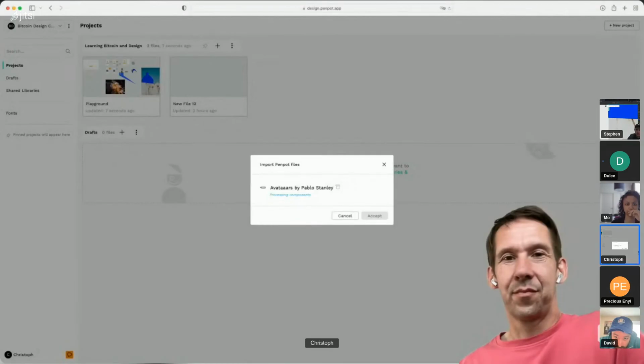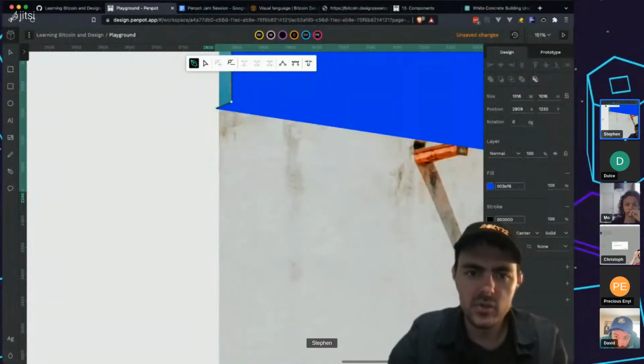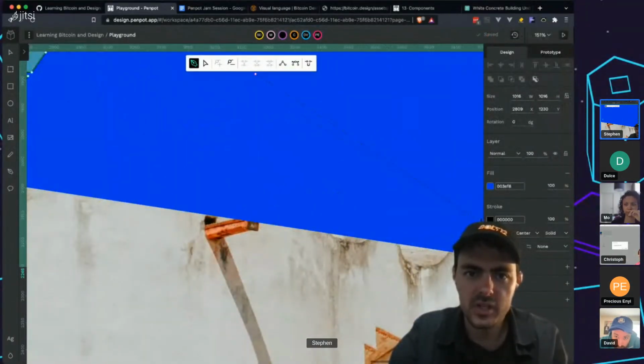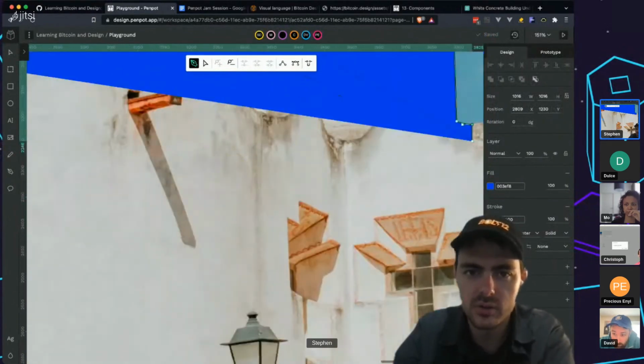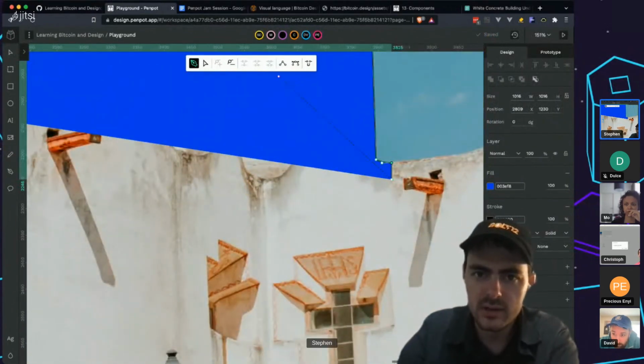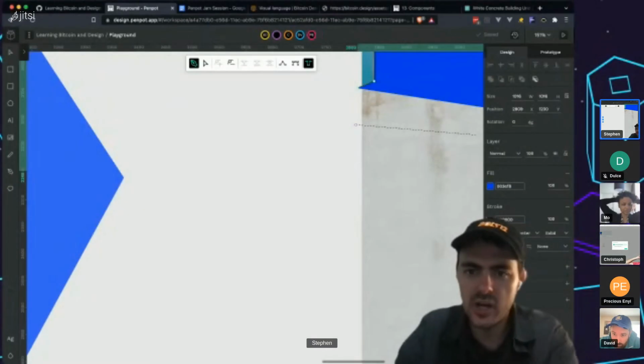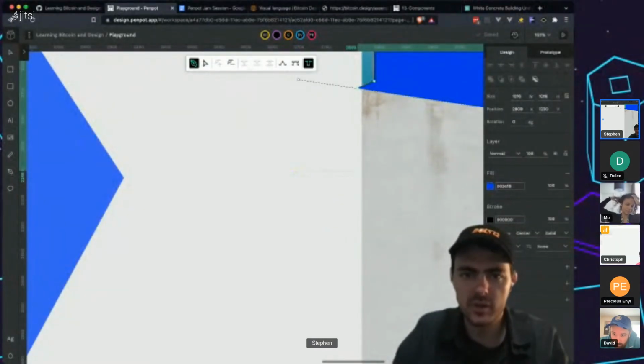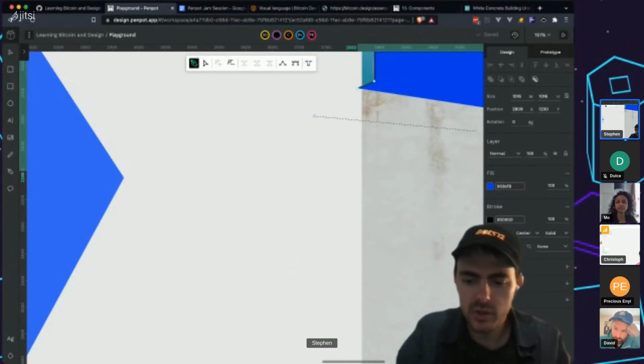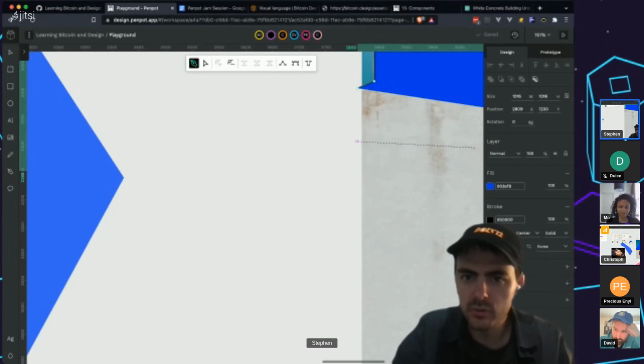What was it? So apparently, when you have the pen tool on, there's this little contextual menu that appears that I didn't notice because I was so focused on my cursor. And this option here called Snap Nodes was on. I'm wondering if it's because I tried holding Shift to make a straight line the first time I used it, or maybe I accidentally pressed Command apostrophe or something. But that was on. Now it looks like I can move a little more freely when I have that off. In this case, I want it on.